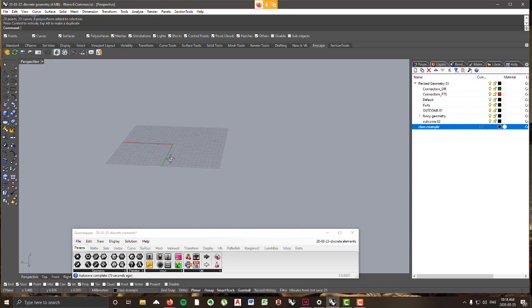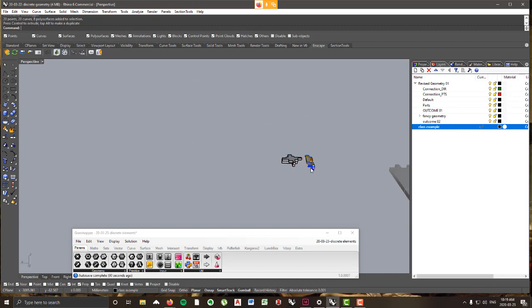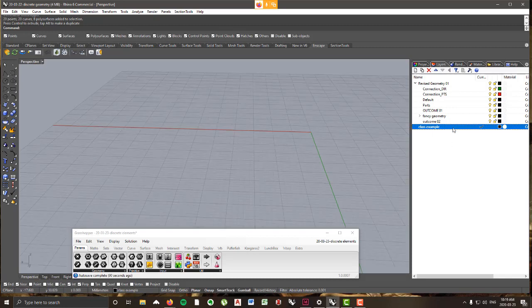So what I'm going to do is set up a very, very basic component and a very basic set of rules, and then I'm going to start adding some complexity to it to show how you can start thinking about these things and how you can start building them up. So there's a few things we need. To define these rules, we essentially need connection directions and connection center points, as well as the piece of geometry itself. So I'm going to make 3 layers under this class example.